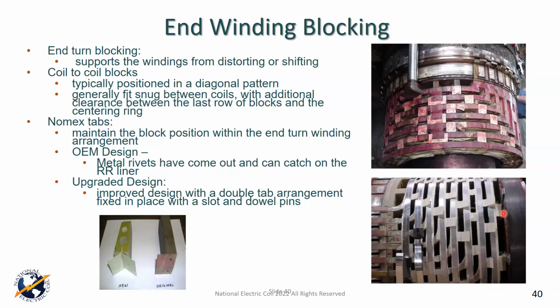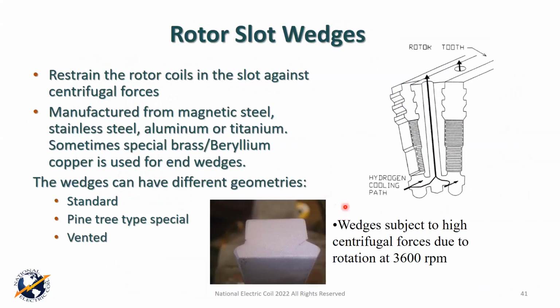And if it does butt up against it, it'll cause a bow in the rotor because it's being mechanically restrained, and it'll exhibit in high vibration. So it's important to understand this in relation to coil to coil: you want it pretty tight. You've got to leave clearance at the end so this machine can expand and contract and allow Mother Nature to do her thing. So those are important things I wanted to mention to you.